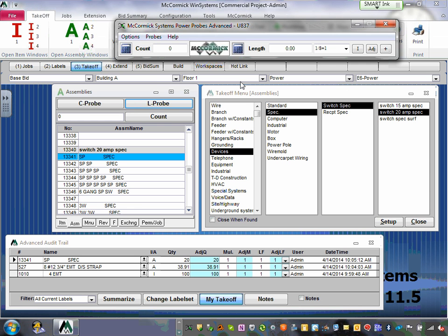Ladies and gentlemen, any comments about using the probes or using the counter? This is your takeoff. You guys can spend 90% of your time putzing around with this. Don't start taking off unless you need to draw the circuit. How are you going to circuit these guys for me? There is a lot of circuits. You're going to group the circuits together in the ceiling with junction boxes. My expectation is to see a junction box in the ceiling. How are you going to put your junction boxes, and how are you going to group them together?